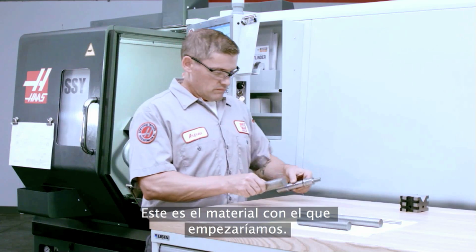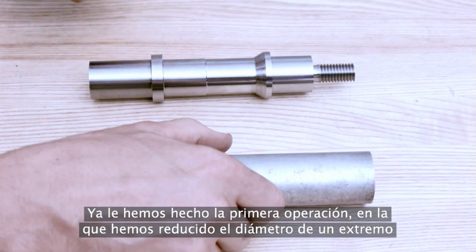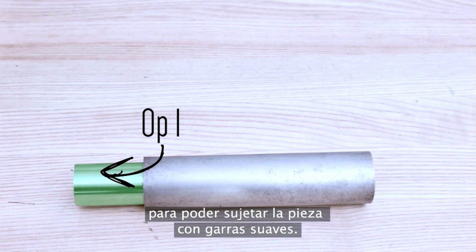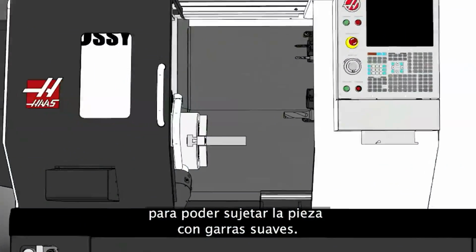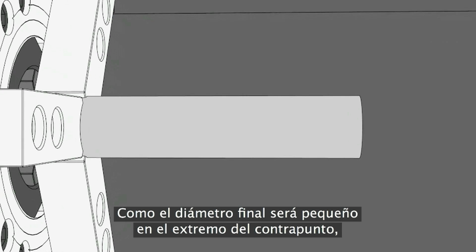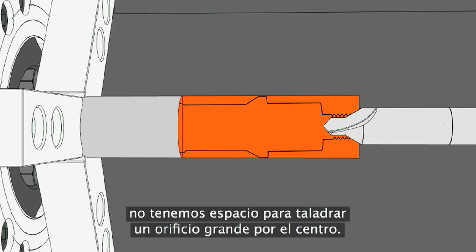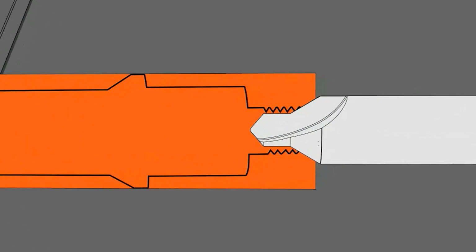Here's the material we'll be starting with. We already completed Op 1, where we turned the bar stock down so we can grip it with our soft jaws. Because our finished diameter will eventually get small at the tailstock end, we don't really have room for a large center drilled hole.